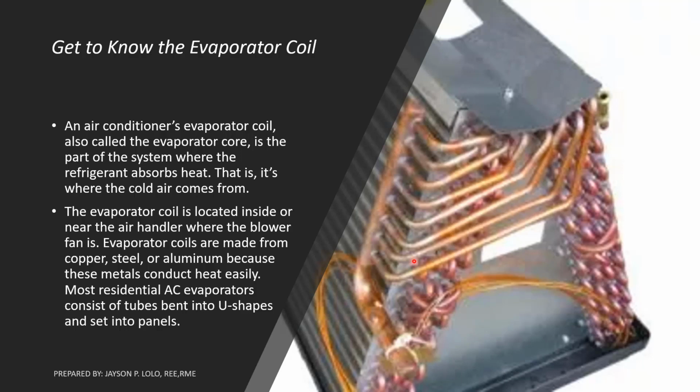Remember that. Instead, they use refrigerant or coolant to absorb heat from the air, carry that heat outdoors, and release it into the air outdoors. The refrigerant circulates continuously to remove more and more heat from your home until your indoor air temperature reaches the one you've chosen on the thermostat.